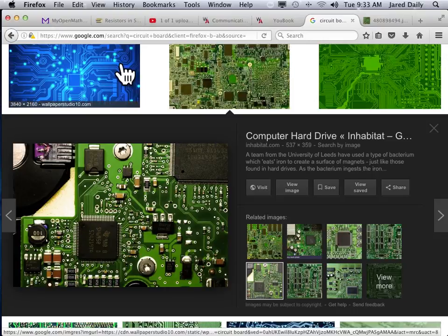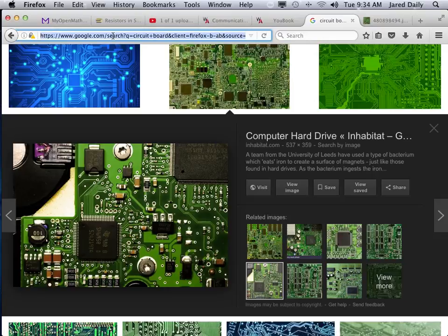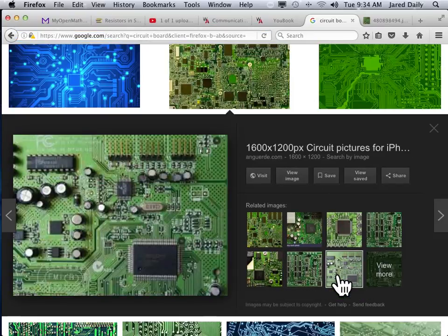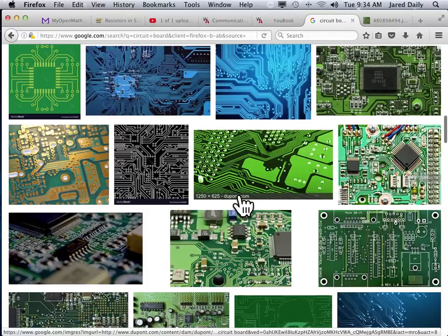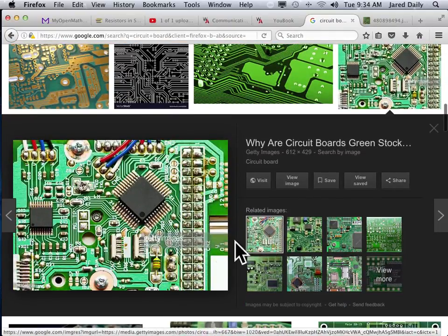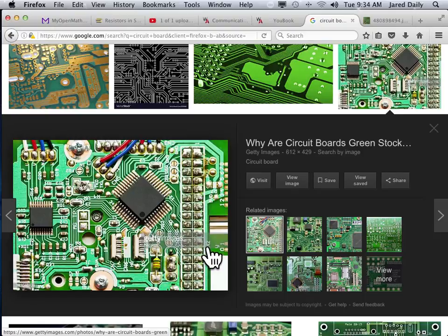And resistors come in all shapes and sizes. Those are what we call surface mount resistors, but there are other types of resistors that are much different than that. Let's see if I can find you, no, not on that board. Sometimes you have to have a bigger resistor. So here is a bigger resistor. This is a standard, what we call carbon film resistor right here. It uses stripes on it for a code to tell you what size the resistance is.